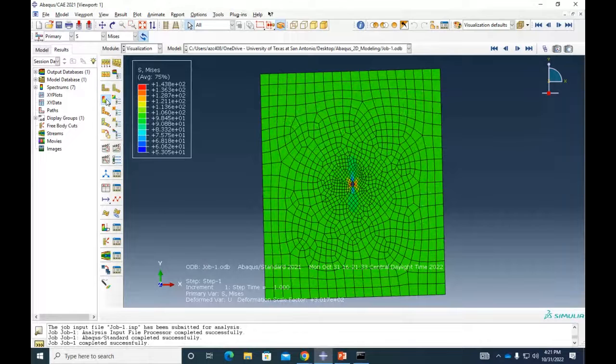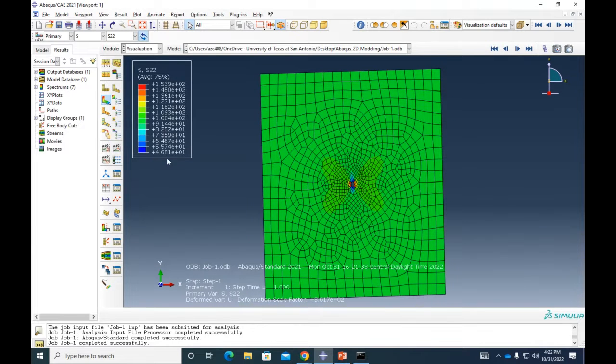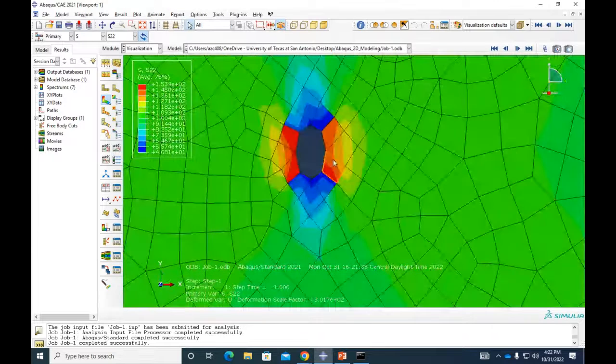All right. It's rotating. I'll get back to you, but the fact that it's rotating doesn't affect the solution. All right. So what we're gonna do here is check the stress in the 2-2 direction, right? Because we are pulling in sigma YY, right? That's definitely this remote stress that we are applying here. So I'm gonna go here to primary, and I'm gonna check the stress, which is this S, and I'm gonna check S22, okay? And then I'm gonna go and see what the stress in this node is, all right?